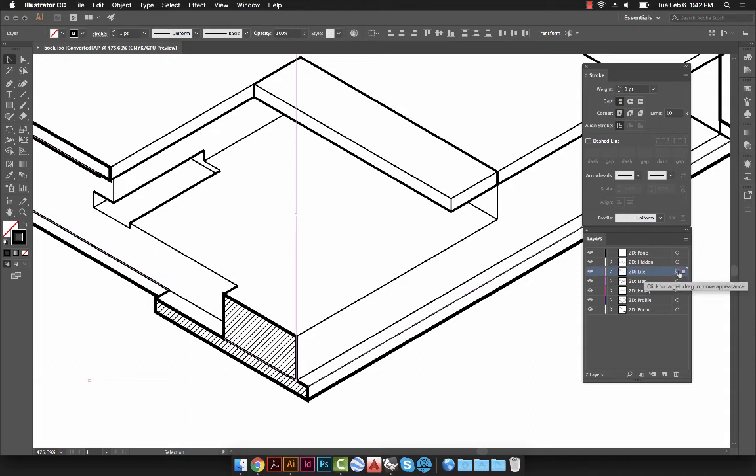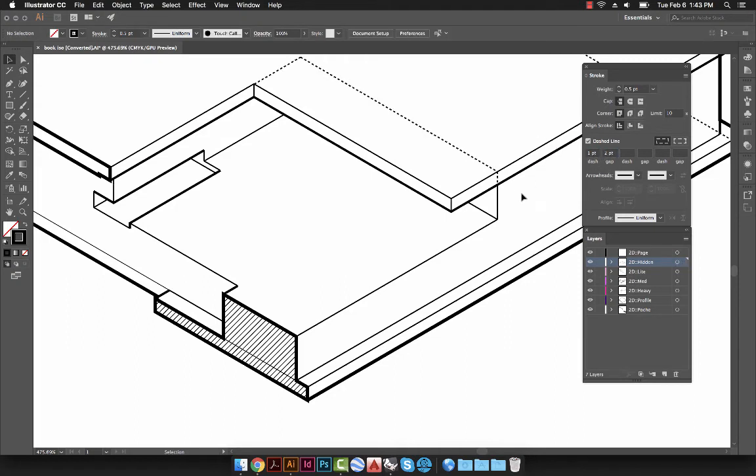I'm just going to set this up kind of off the top of my head right now. So the light lines are set to 0.25. So again, that's the kind of change in material here within the poche, and also within this area that had been booleaned out. And then I will set my hidden lines to 0.5, but I'll go ahead and give them a dash. I'll just do a 2-point dash, or maybe I can do a 1-point dash, kind of a tight dash there.